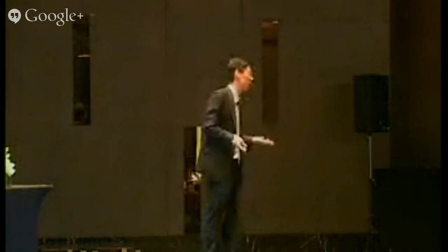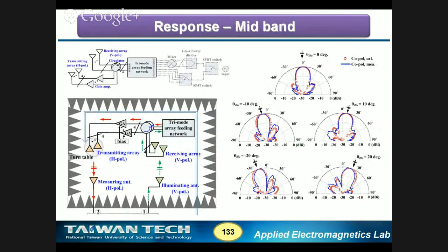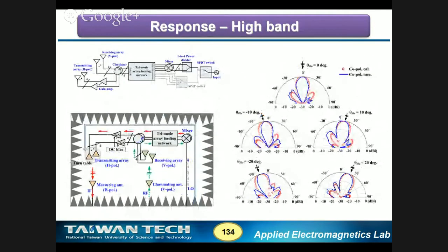Perfect, almost perfect. The bottom matches. It is a beam switching antenna. And in the mid band, of course, we did not incorporate the bidirectional amplifier, but it is still a Van Atta array with radiation directive. The incident signal is here, and the reflected retransmitted pattern is also in the same direction. Okay, and in the high band, once again, it is a radiation directive array.